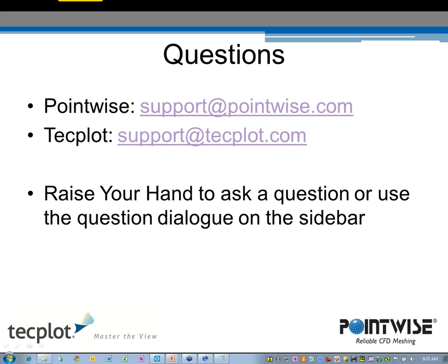There was a question around whether a Pointwise structured mesh is possible or not. Yes, absolutely. That's the bread and butter of Pointwise, our meshing algorithms, and you've seen it in action around the blades. That was a hyperbolic structured extrusion from the blades, and then Travis filled in the rest with an unstructured mesh. I think there was one slide where I also showed a fully structured mesh. So it has true fully structured meshing as well as unstructured and some hybrid, and they can all be combined and work together in the single interface.